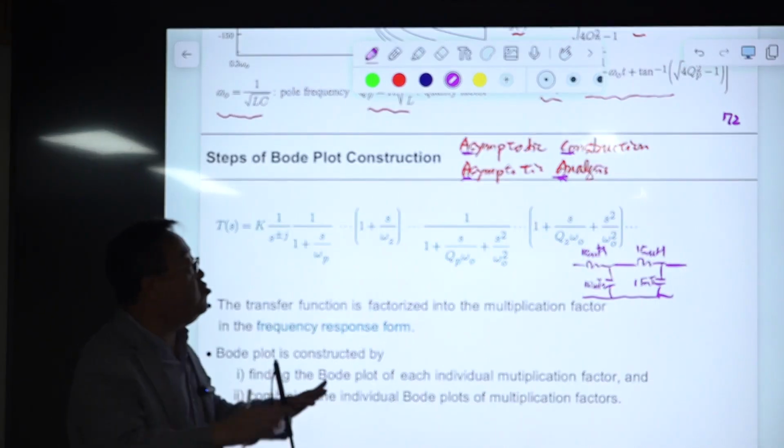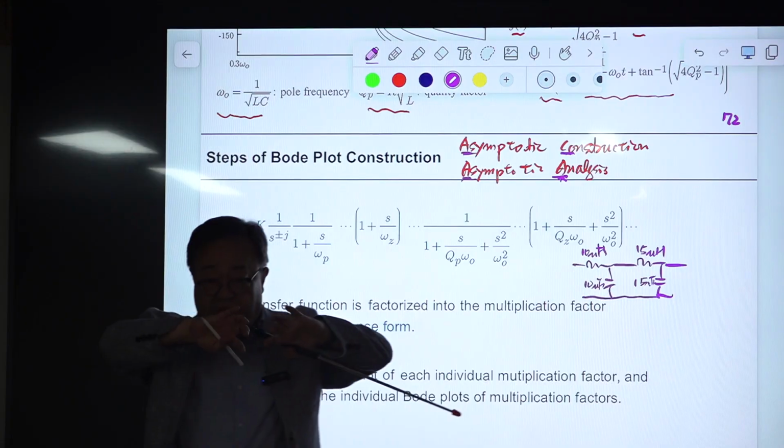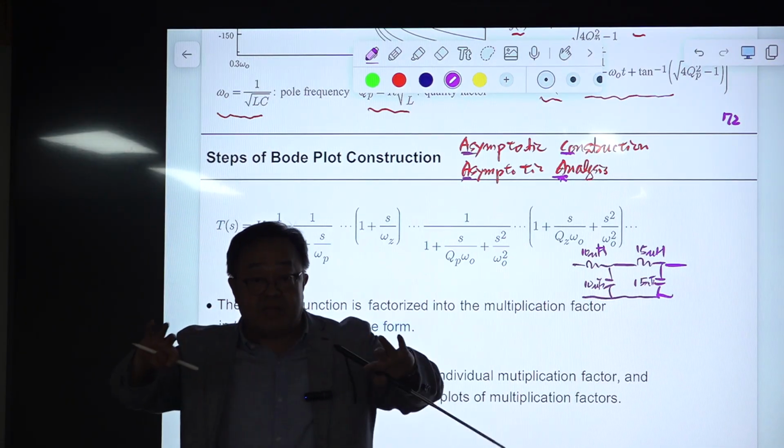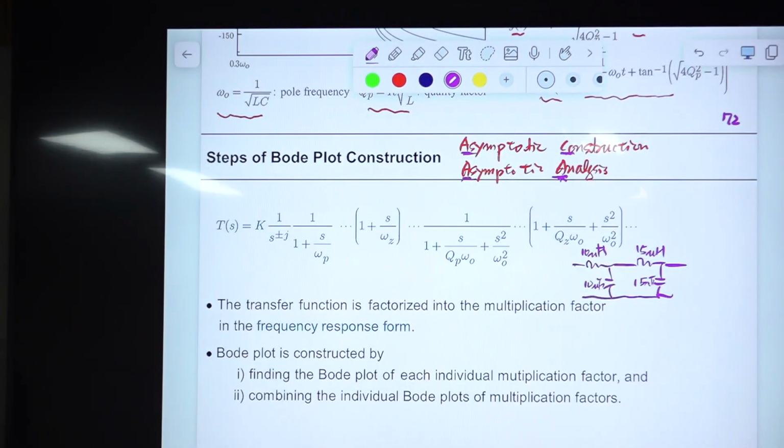So to have this, you have to separate the time constants of the circuit in advance. Suppose you increase this. Okay, you don't want to increase something, so you decrease this to 0.1 microhenry, and you decrease this to 0.1 microfarad.